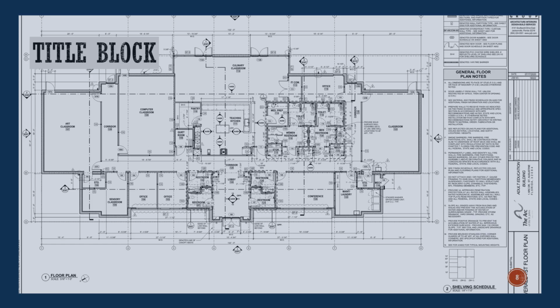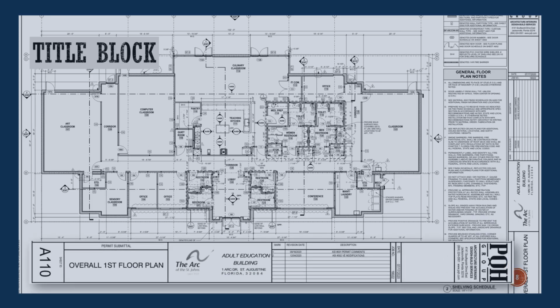The title block is a rectangular box usually present either at the bottom or on the right-hand side of a drawing sheet. This box contains various information such as the title of the drawing, scale, the logo, or information about the company and people associated. The project, which includes name, address, and date. This helps in tracking the revisions made over time as this drawing goes through several changes, and those changes need to be checked upon regularly.